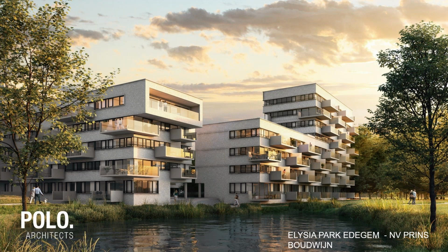Yeah. Well, that's fine. I think the whole product, BIM 360 Design, there's so much to it, yet very easy, but people have to start somewhere, right? And I think if you're used to working with central files, save to central, reload latest, that's the first step, and that's what I would advise, right? It's what you're used to, that's what you can bring forward into BIM 360 Design as well.